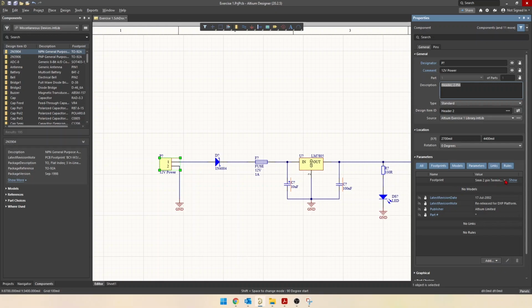This shows a list of all of the footprints for that component that have been added in the integrated library or in the schematic library. So if I click on this, this has a list of various footprints that have been added to this library. In this case, we're going to choose, say, a 5mm terminal block to be our footprint.